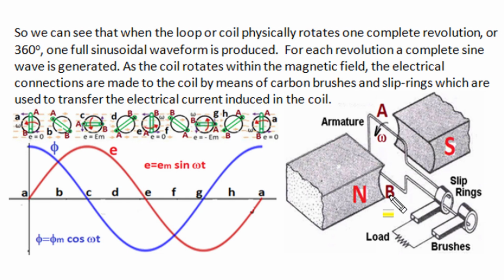So one rotation of the rectangle loop produces one complete cycle of induced EMF, and the connections of the rectangle coil are made to the external load circuit through slip rings and brushes, and we can utilize the induced sinusoidal EMF in the external load via the slip ring and brush arrangement in this generator.